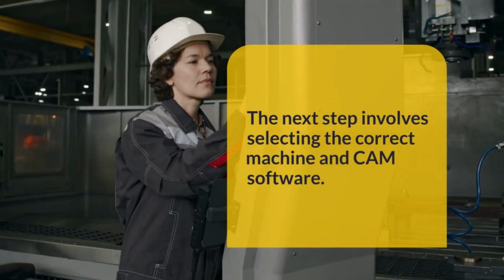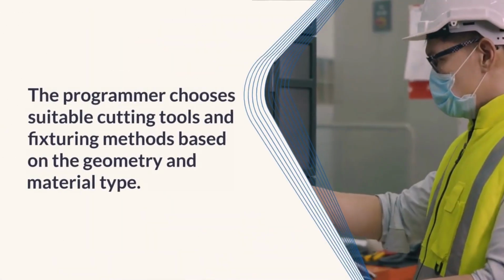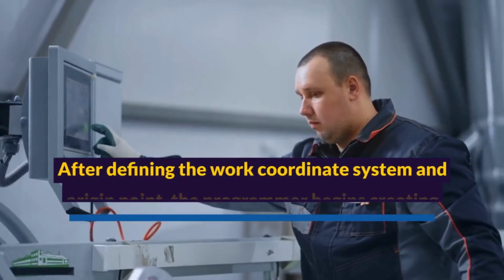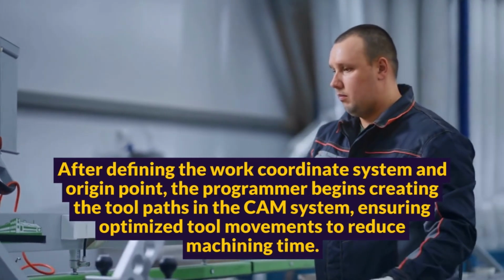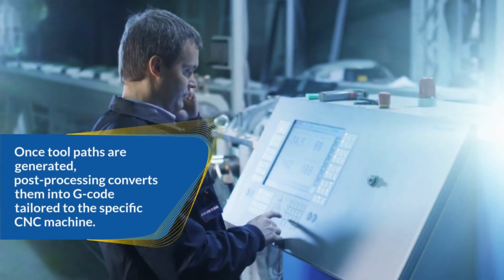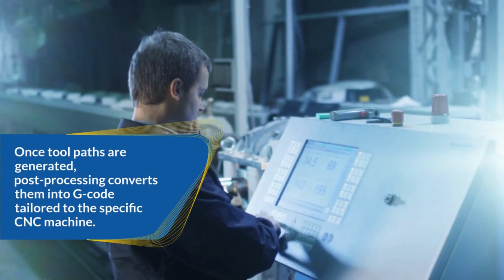The next step involves selecting the correct machine and CAM software. The programmer chooses suitable cutting tools and fixturing methods based on the geometry and material type. After defining the work coordinate system and origin point, the programmer begins creating the toolpaths in the CAM system, ensuring optimized tool movements to reduce machining time. Once toolpaths are generated, post-processing converts them into G-code tailored to the specific CNC machine.